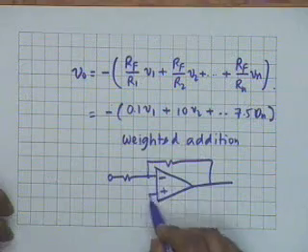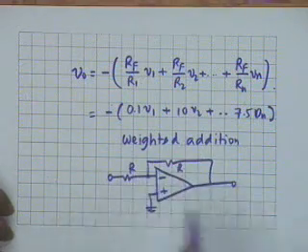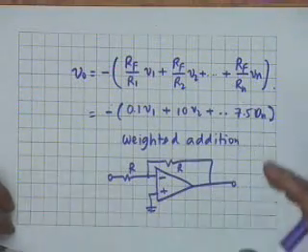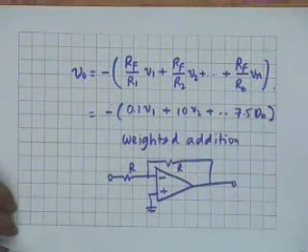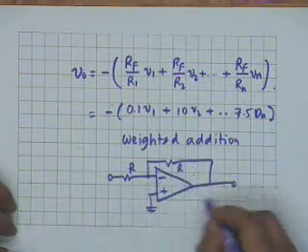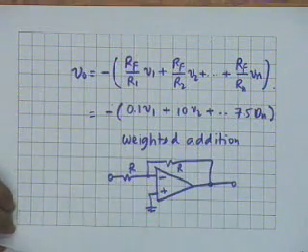Minus, plus, this is grounded, and this resistance is the same as this. So what I do is connect in cascade another stage like this, and then this is simply a sign inverting stage. That means a stage with a gain of -1.